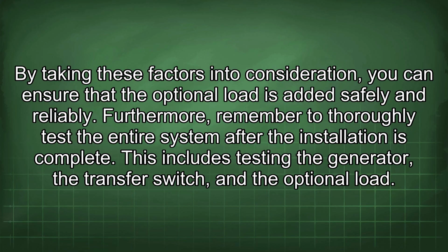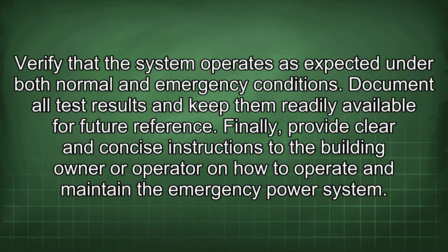Furthermore, remember to thoroughly test the entire system after the installation is complete. This includes testing the generator, the transfer switch, and the optional load. Verify that the system operates as expected under both normal and emergency conditions. Document all test results and keep them readily available for future reference.